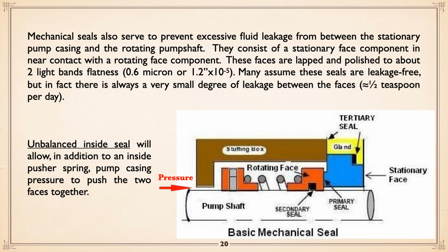What is the magic of mechanical seals? Basically, they have a stationary face, on this drawing it's blue, and a rotating face, which is orange. The stationary face, by the way, is held to the casing with seals, okay? There's different ways of doing that, O-rings, whatever, but basically it is sealed. And the rotating face is pushed by a spring, and you can see there's a piece at the back. That little gray thing would be a set screw to hold that so it spins.